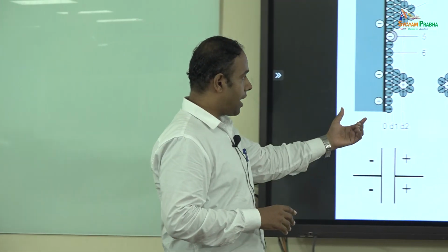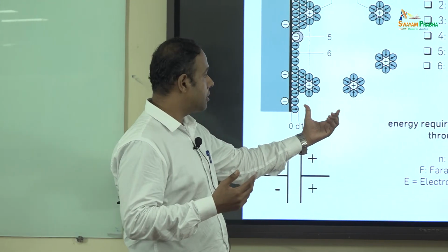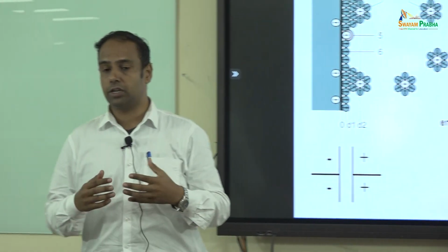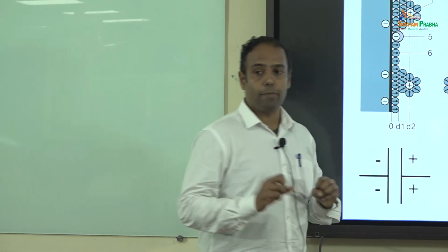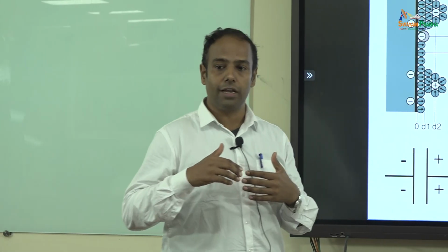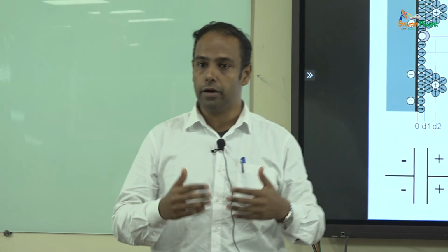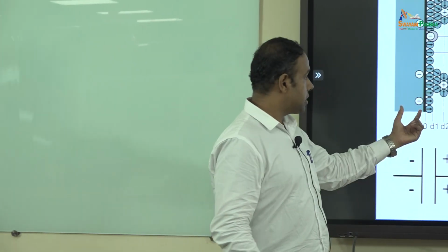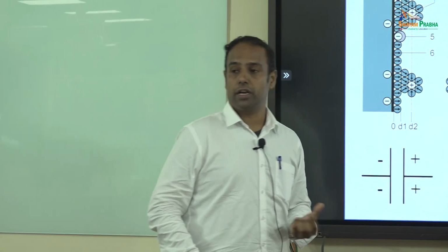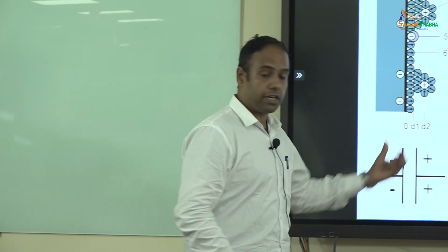But now when I assume real conditions, apart from ideality, that I have an electrolyte, the electrolyte is again a charged species which contains an anion and a cation. When charges are present on the surface, the metal has a certain willingness to give electrons based on its thermodynamical aspect. For example, zinc is more willing to give electrons than iron. That's what we know. Now when electron transfer happens, the surface at the electrode and electrolyte interface is what we name the electrified interface.